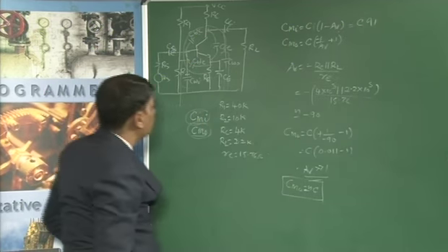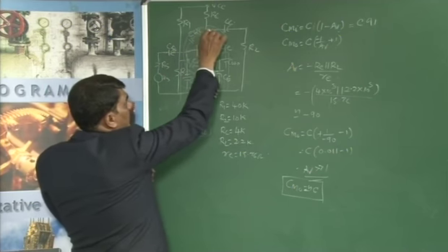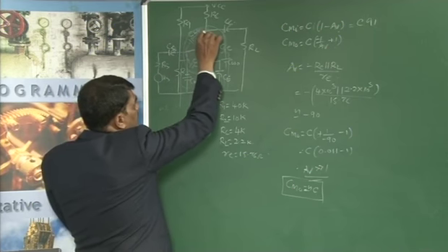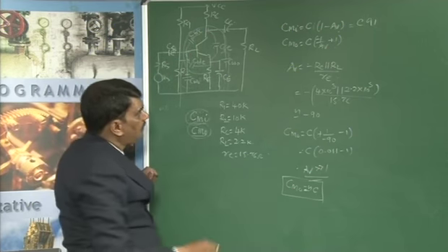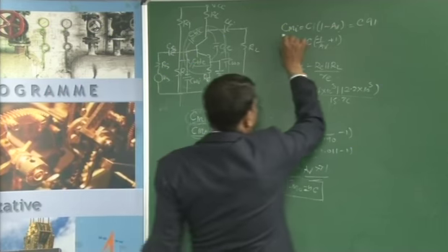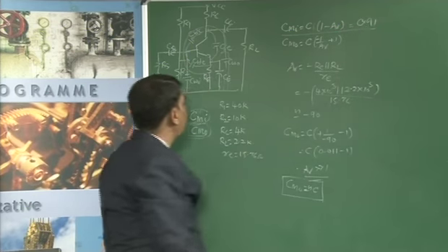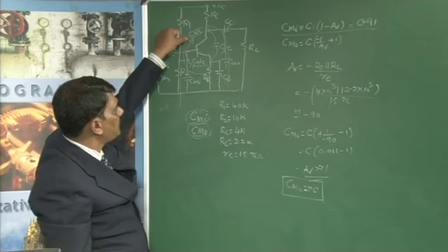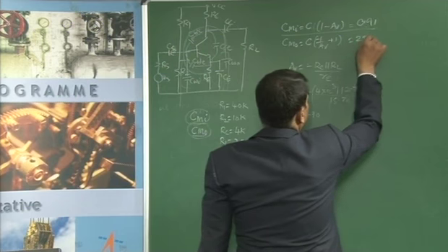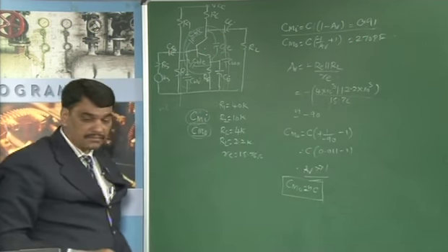This implies that the capacitance at the input side increases due to the feedback capacitor, or the junction capacitor between B' and C. Because of that reason, f_HI also decreases. Therefore, you are calculating C times 91. If C_BC is about 3 picofarad, you get approximately 270 pF for the transistor.